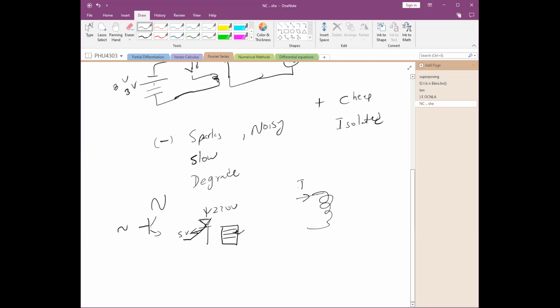Now, the property of the inductor is, if you try to push the current, it will try to oppose it. But when you are already having a flow of current, if you try to stop it, it will try to regenerate it. So the problem with the relay is when you try to switch off its current in the coil. Let's say you have a switch here.